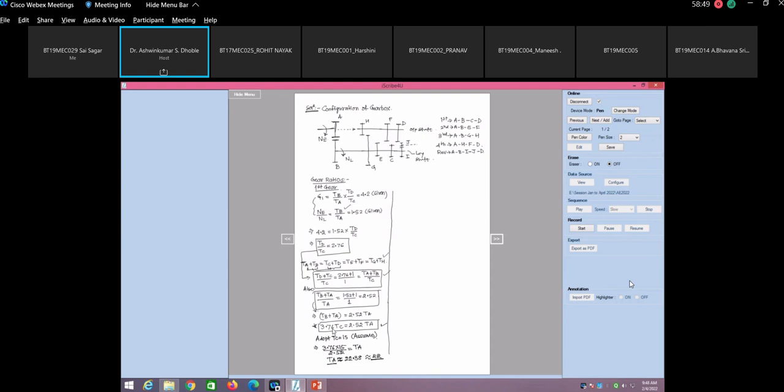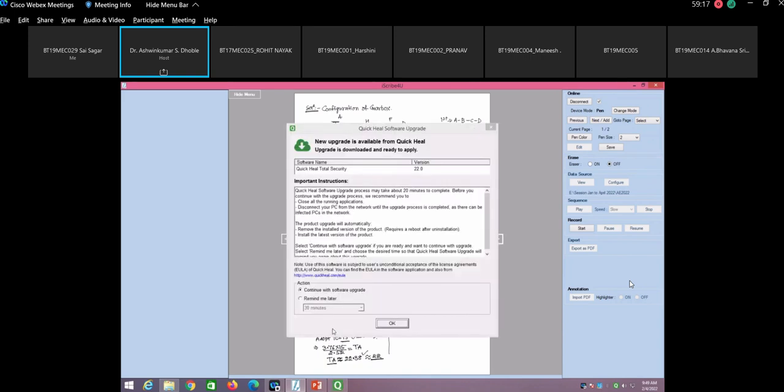You may assume 23 here as well, but since in this problem it should not be more than 22.5, let us assume it is 22, because gear teeth cannot be in fraction. Sir, are you in agreement up to here? Instead of this 15 you can assume 18 as well, 17 as well, that is your choice.